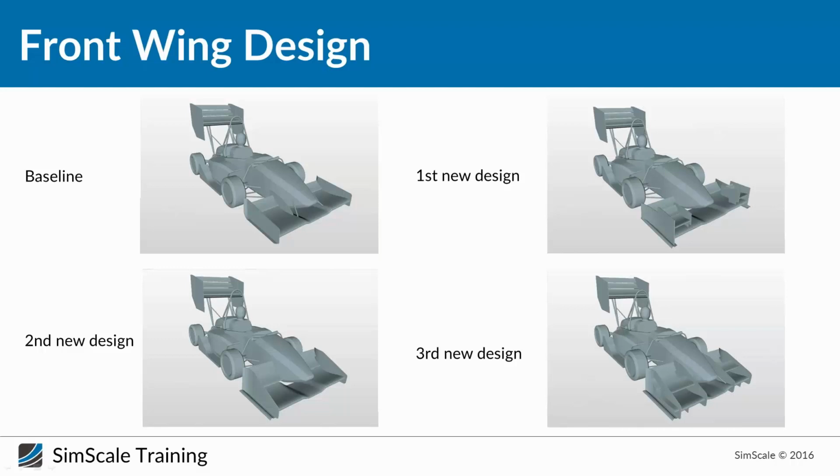Why? Because this element is relatively small compared to the main wing, so this element will generate downforce, but the downforce generated by this element is really small compared to the downforce that we have lost by creating this element on top of the front wing.